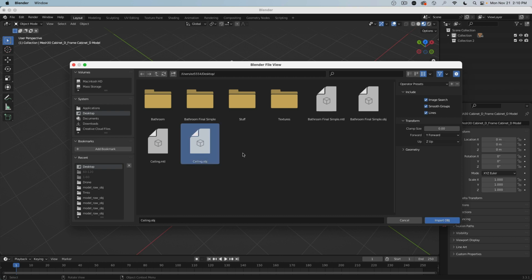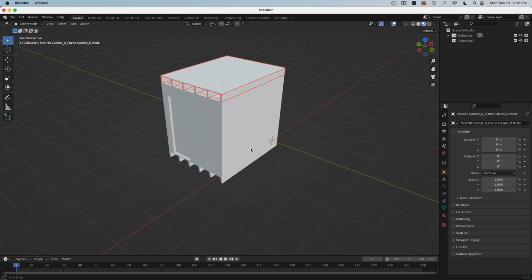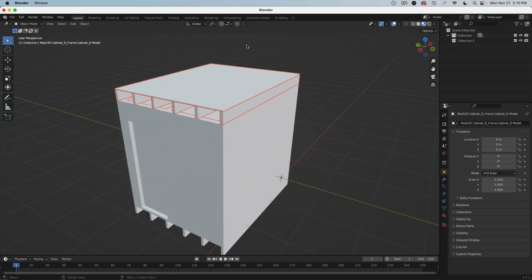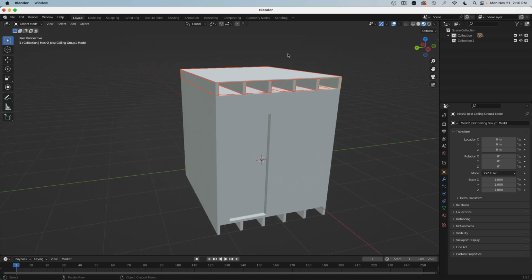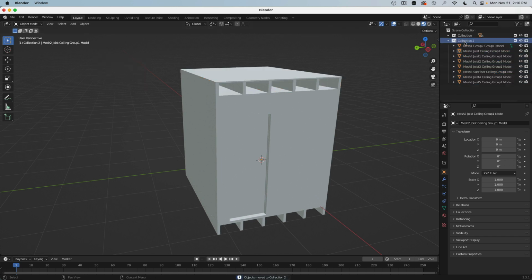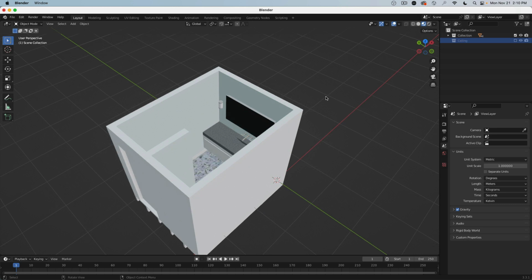Then import the ceiling, same settings, all the same. Import. There they are. You see, perfectly, they even snap right into place. And with these objects still selected, I left mouse button and hold shift, I can select all those, and then I can press M for move to this collection too. And for example, this collection now I call ceiling. I can turn this off for the moment. You see, that is actually how easy it is, and also to bring additional elements over.